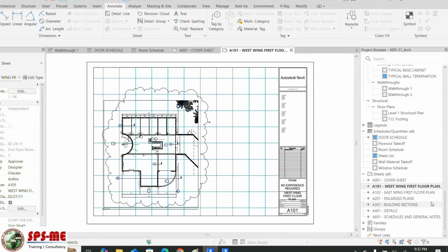So this title block, can we also import it from the model? No, the title block you can actually create, and if you want, you can keep that as part of your project template. But sometimes there will be differences, because sometimes the client logo, client name, everything we have to put there, right? It will differ, so we can import according to the client also. So in those cases, whenever it's required, we have to create it and load it. Create it in the sense that most of the things are already there, but you just have to change to whatever format you follow. Then the name and all those things you can change anytime. Okay.